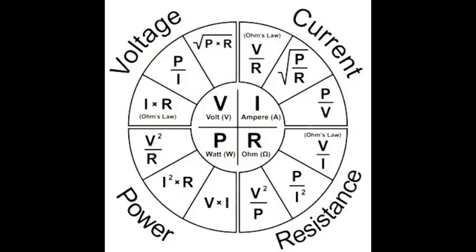So for example, when my students are wiring a bathroom and they have multiple loads to connect to a circuit, if they understand Ohm's law and circuits, they did their load calculation. If they just ran one circuit and put all 4 loads on it, I will ask them, why did you run only one circuit? Oh, well, my lights turned on, my fan turned on, my exhaust turned on. I said, yeah, but you're overheating the circuit because you didn't take into consideration that all of the amperages used on the circuit are going to add up. This is something that as electricians we need to know, and we always need to remember what happens to our circuits when we wire them a certain way.